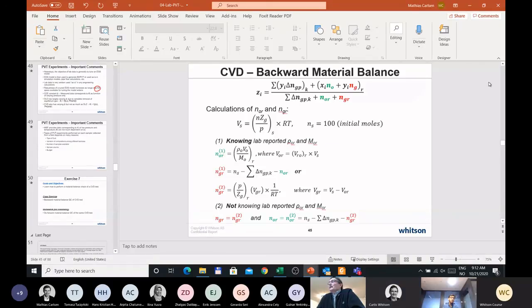And I think the second, because of the uncertainty in the compositional measurements of removed phases, of the removed gas phase in the CVD and the DLE, comes from there being such a small sample taken out often, and getting the composition of that right, and in the laboratory there are a lot of reasons for the uncertainty there. But you sometimes want very accurate PVT data for a range of compositions.